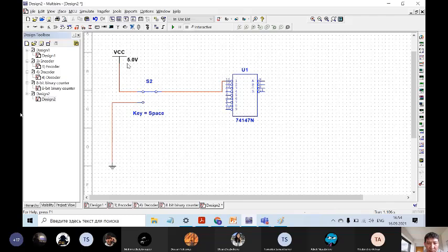In order to activate it, to give a signal, I need to apply a low value. You already asked how we can apply a low value. Just with the switch, can you see? And now you apply low. Actually, this bubble here means that to activate this pin, you need to apply low.